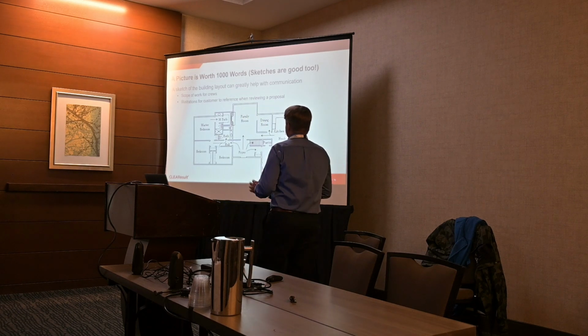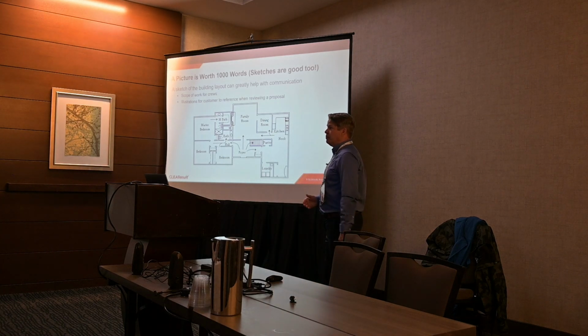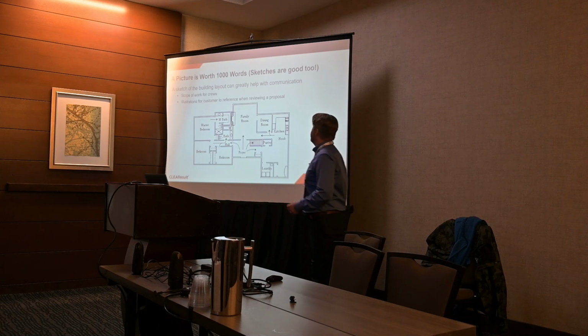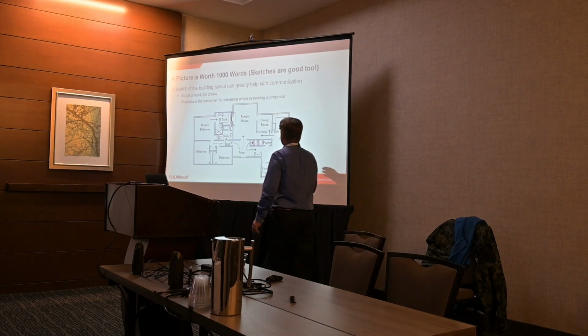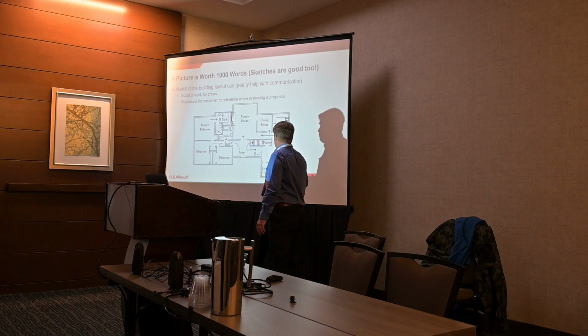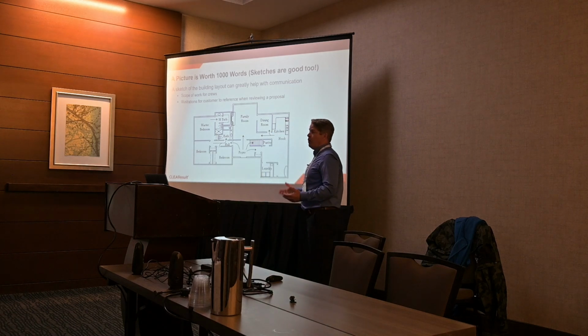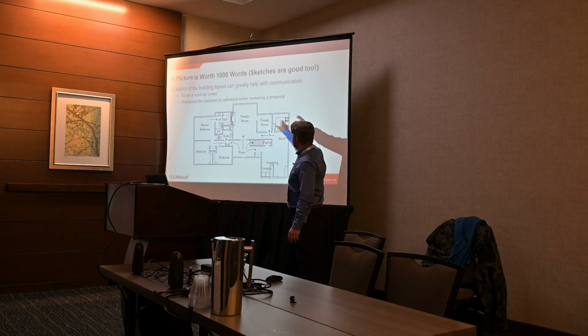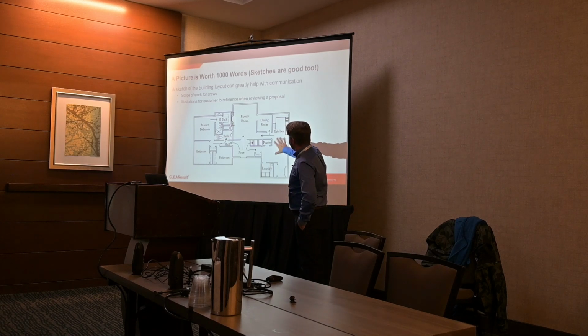So this is probably something that you've learned, especially now with digital cameras and stuff. It's so easy to take a picture of anything that you want to describe to somebody, right? So they've always said that a picture's worth 1,000 words, and sketches are pretty good too. One of the things that I always did when I did an audit was we had to figure out what the wall areas and ceiling areas were, because we were always specifying insulation. So we would just start in one corner, and we would measure out a sketch on a piece of graph paper, and we would dimension it, and then we would put all the different details on it.